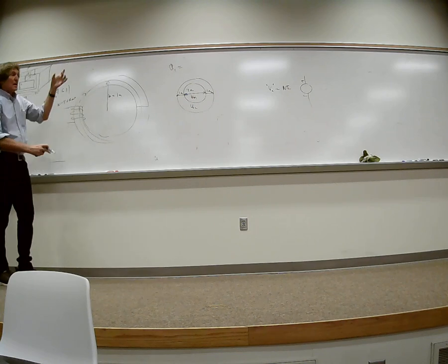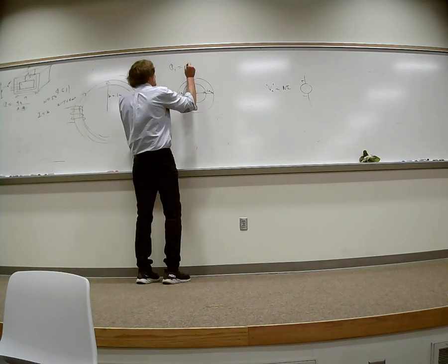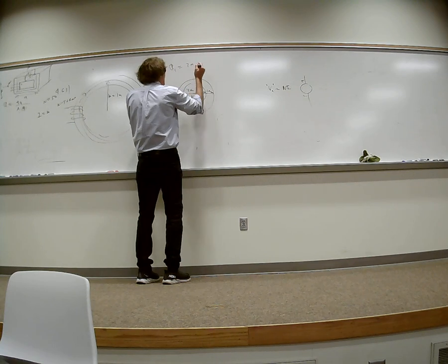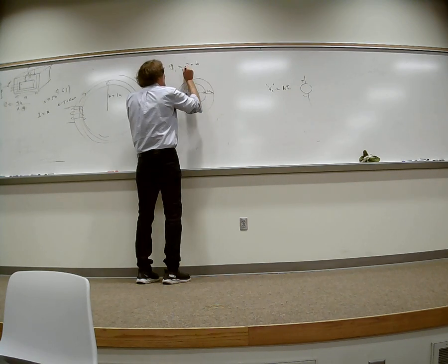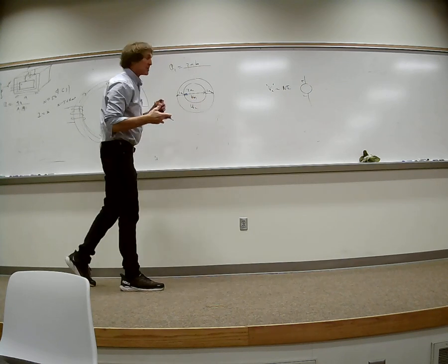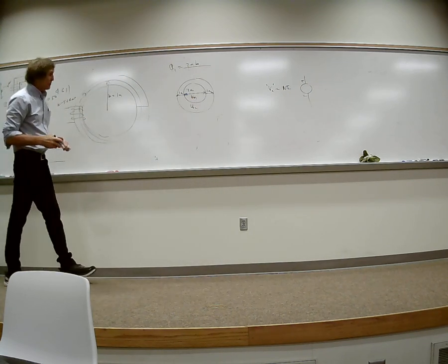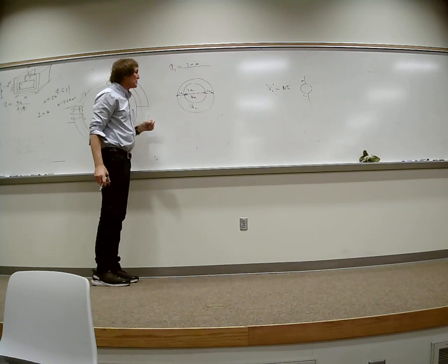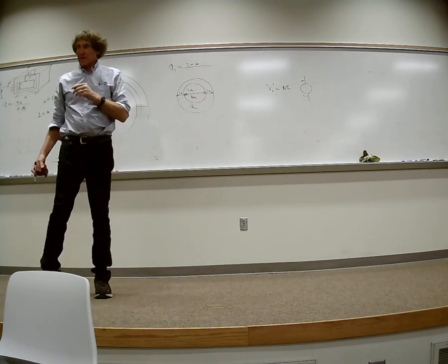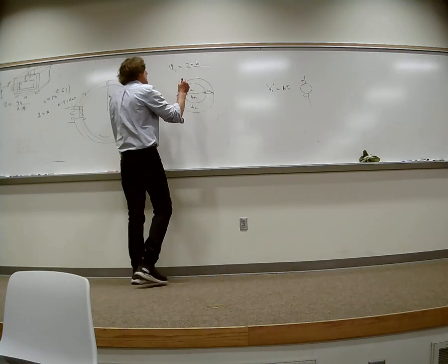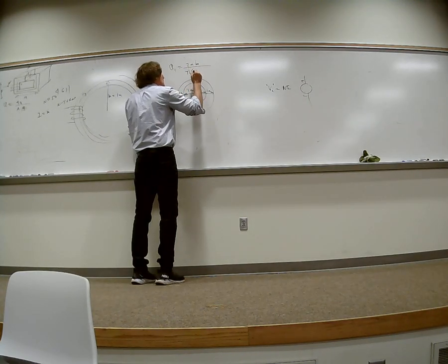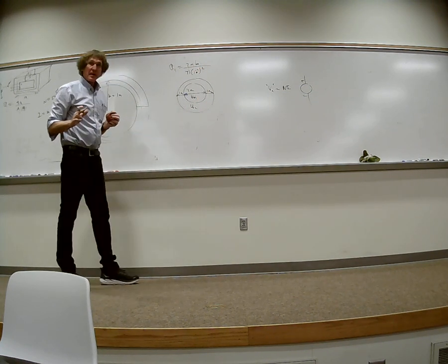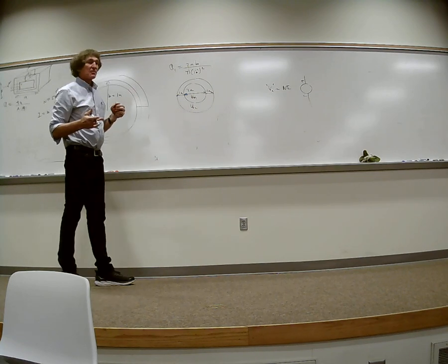You all follow me? So that's going to be equal to 2 pi times the actual value of b. I'm going to leave it as b. Now I have to divide that by the cross-sectional area. I'm going to talk about the reluctance 1 being associated with this inner material that has mu relative 1, right? So that area, if that has a diameter of 2 centimeters, has a radius of 1 centimeter. And the area would be what? Pi times 10 to the minus 2 squared. You all with me on that? Now b happens to be 1, so it's irrelevant.